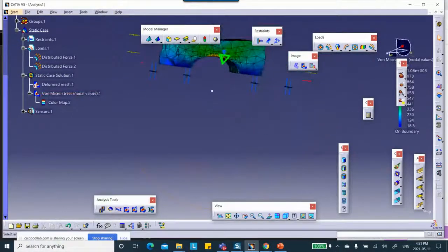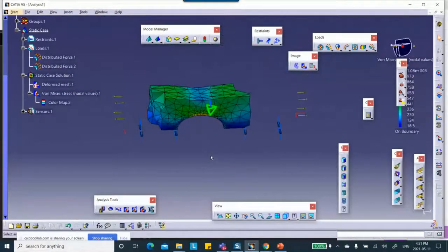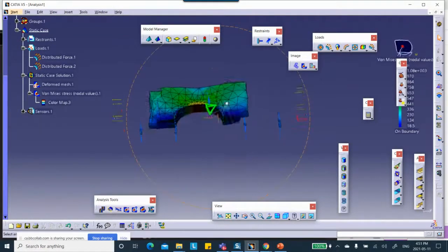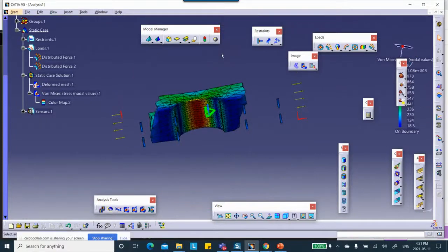The purpose of a group is you select where you want to watch your results. And under St. Venant's principle, it says, hey, stay away from those two ends because you don't know what's happening at those two ends. You put pressure, you put load, so that's ambiguous. Okay, stay away from that. Show me where it's important, top and the bottom of the guy.